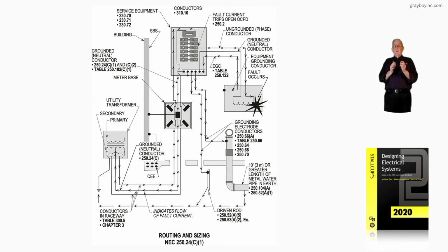Now, that would be the same if you had, say, a metal conduit. It's just that 250.118 gives you a metal conduit as an equipment ground. Meaning what? If you go to the University of Georgia site for testing equipment grounds, that metal conduit will pull about 90% of a fault, a good rule of thumb. The equipment ground will only pull 10%.